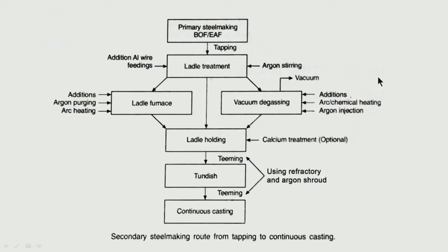The total oxygen content in liquid steel at the final stage should not be more than 25 ppm. If you take all these cares, it can be further controlled to even less than 15 ppm, if you take all these measures and do all the controls.